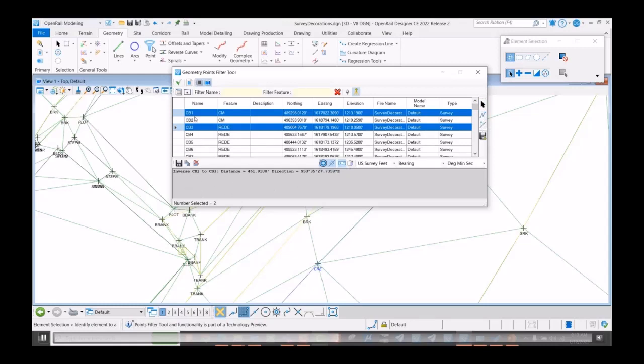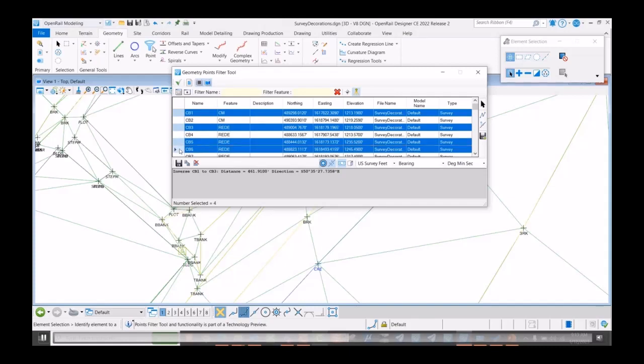You can inverse between the selection. So here I've got 2 points selected. I'm doing a quick inverse, and you can see the results. If I add more points, I can do inverse again, and it'll inverse between those points as well. You can get station and offset information.